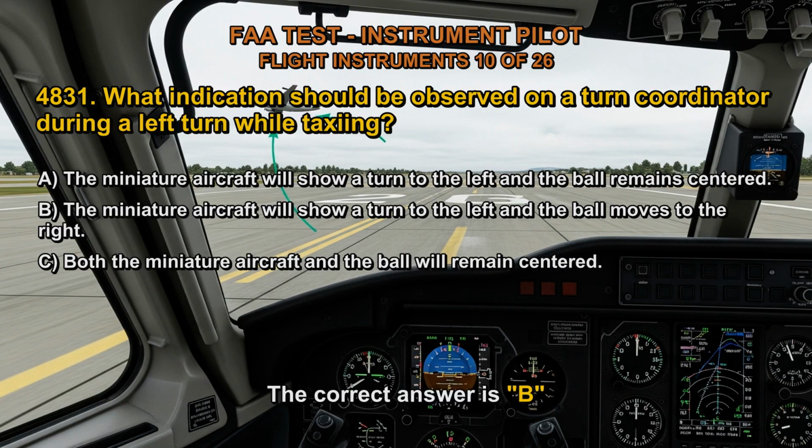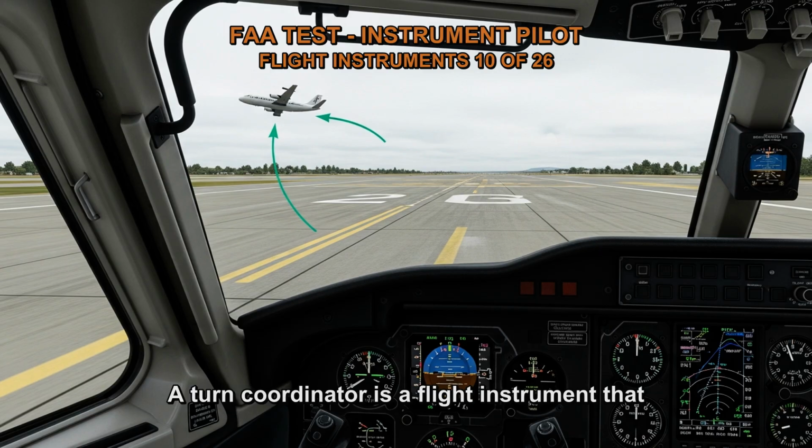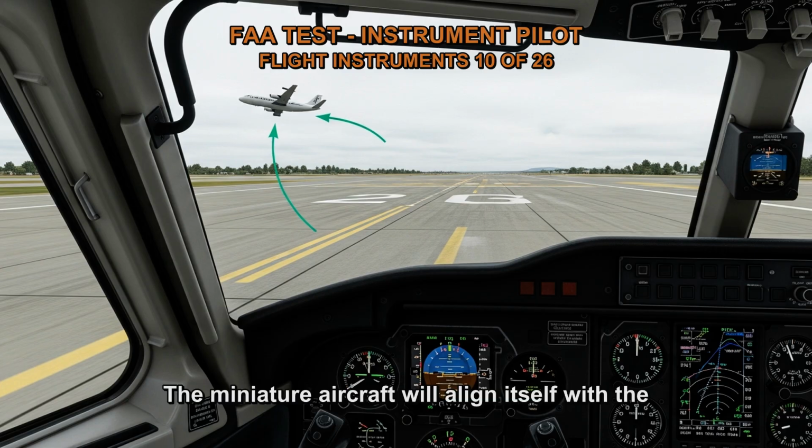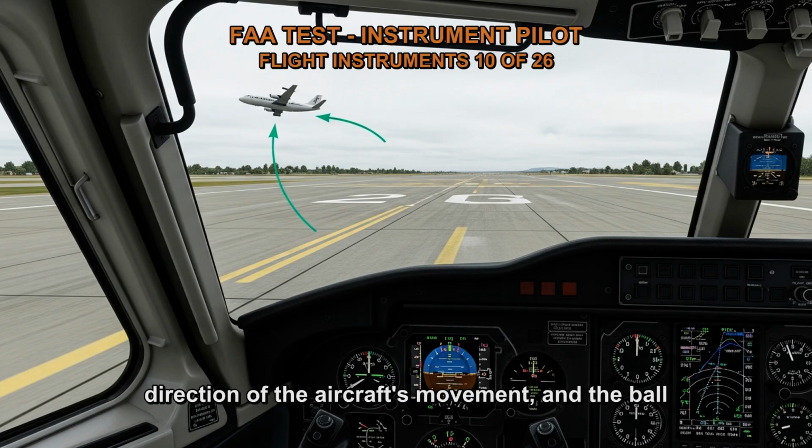The correct answer is B. A turn coordinator is a flight instrument that indicates the rate of turn and the direction of turn. It consists of a miniature aircraft that is free to rotate around a vertical axis and a ball that is free to move within a curved tube. The miniature aircraft will align itself with the direction of the aircraft's movement, and the ball will move to the side of the tube that is opposite the direction of the movement.